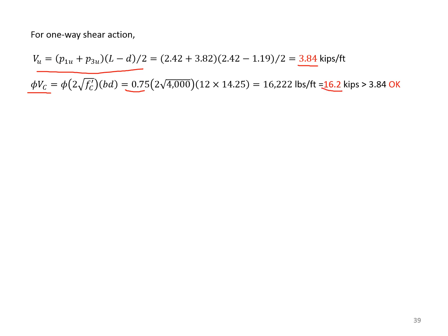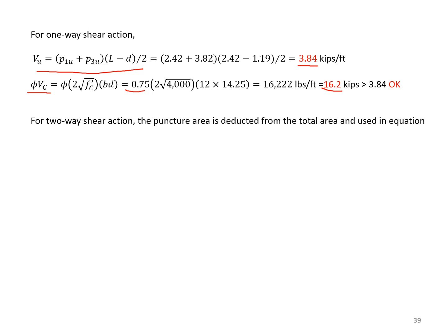These equations are empirical equations, and they do not work out if you want to do the units on those. A lot of our viewers who are outside of the United States, who are not familiar with the ACI code, often ask me these questions. So again, you always use pounds and inches. psi for f prime sub c, you get pounds and inches out. In a lot of equations, ACI has this square root of f prime sub c.